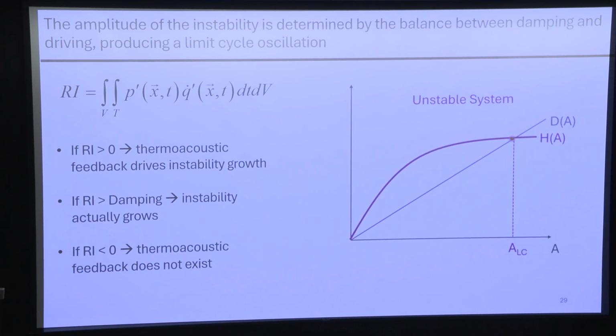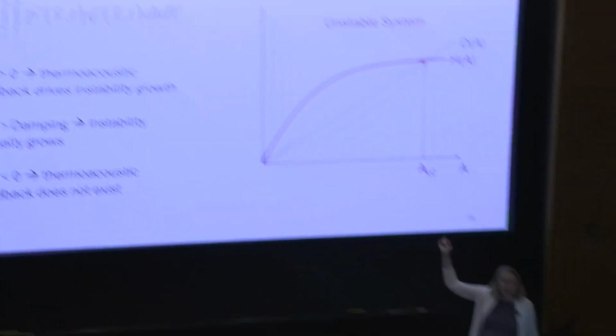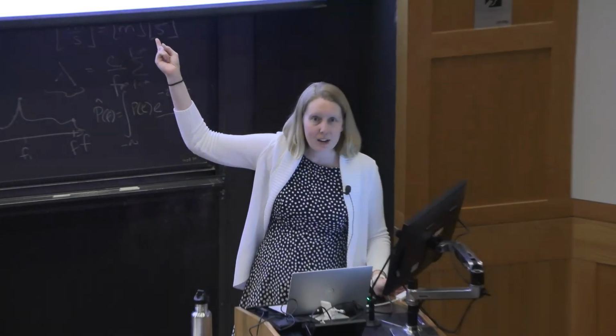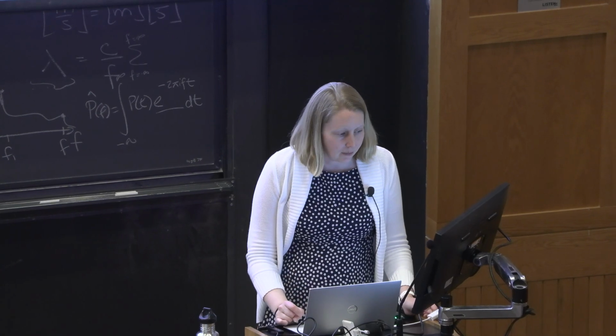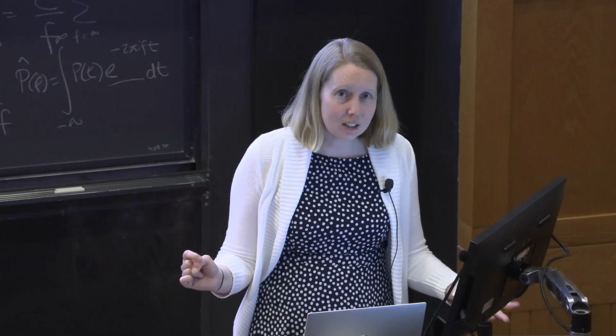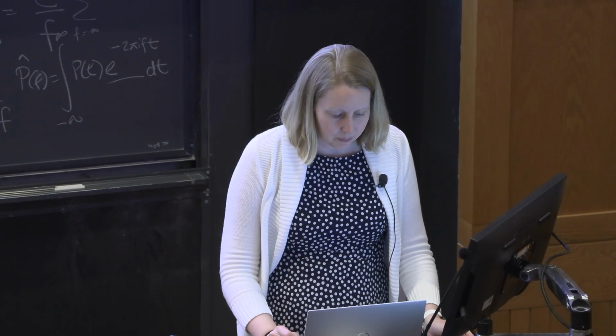So this is called a stable point for the system because it'll just sit here. If I poke at it from this point, it'll go back to that amplitude. But we call this now an unstable combustor because it's screaming, because typically limit cycle amplitudes are pretty high. Show of hands who's taken a nonlinear dynamics course? Couple people. So this is like nonlinear dynamics 101, right? So fixed points, limit cycles, all that kind of stuff. This is one of the reasons I really like thermoacoustics as a discipline, because you get to learn so many things, and nonlinear dynamics is one of them.